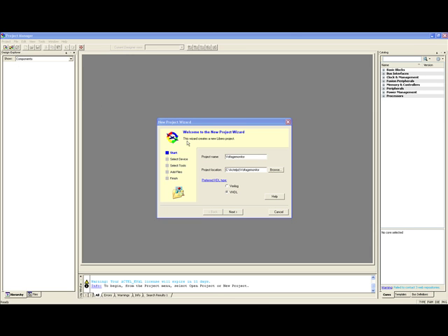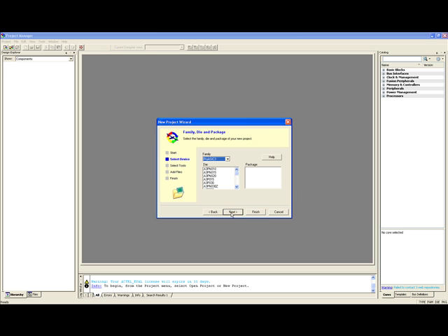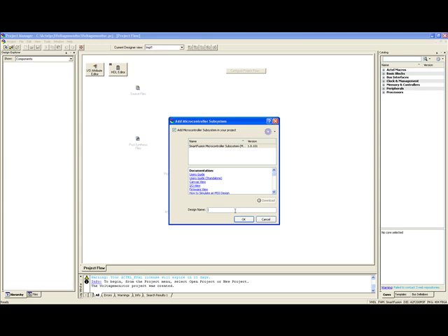Open the Libero IDE New Project Wizard, name the project Voltage Monitor, select the HDL type as VHDL, and click Next. Select SmartFusion, A2F200M3F, 484 FPGA as the family, die, and package type, and click Next. Confirm or edit the integrated tool profiles and click Next. For this project, we will not be importing any external files, so click Next and review all the selections made. Click Finish to create the project.